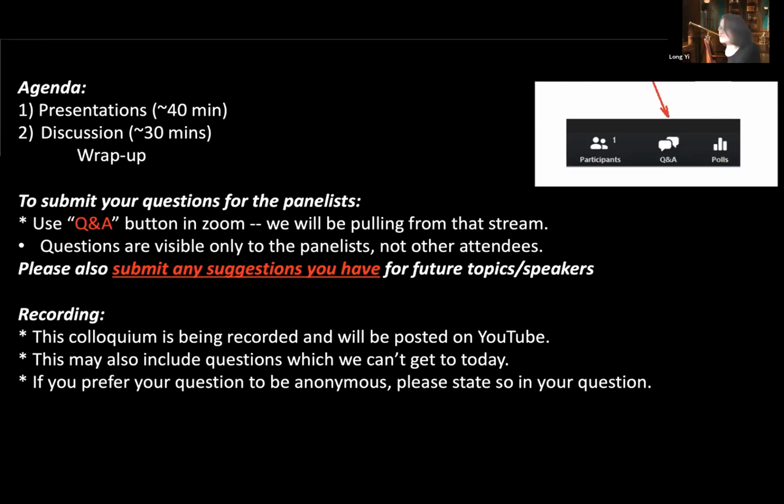There is an issue for a reflective one, because a reflective one only works for summer, but in winter it is also going to reflect. So you have to bear in mind that we're doing the smart window, which means we need a thermal response, or whatever optical response, that is completely the opposite for summer and winter.